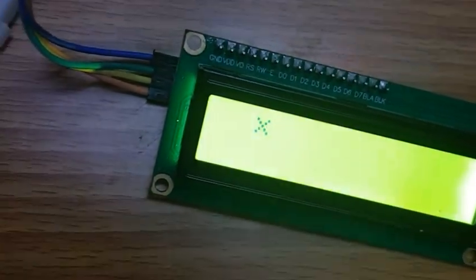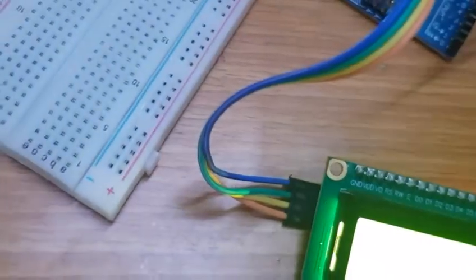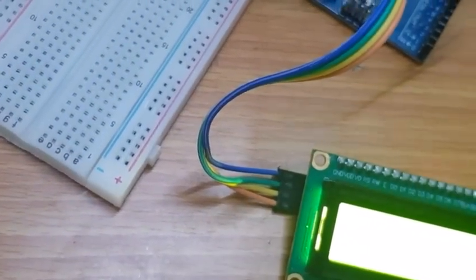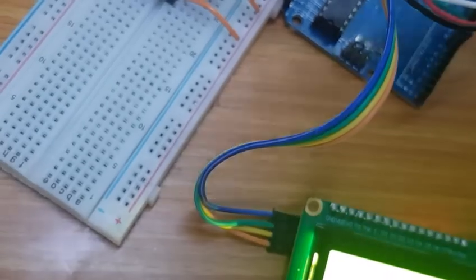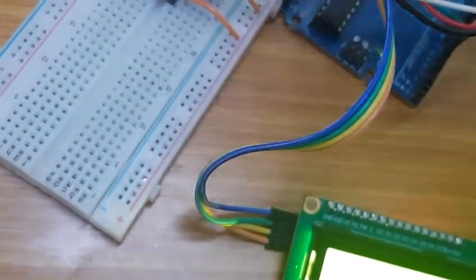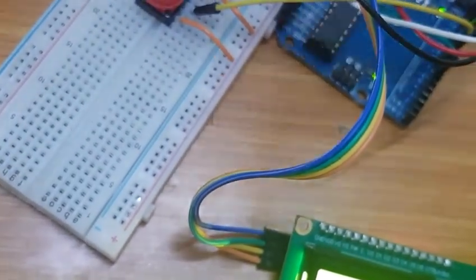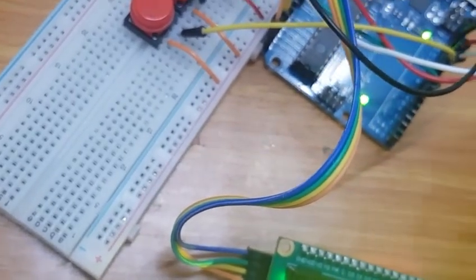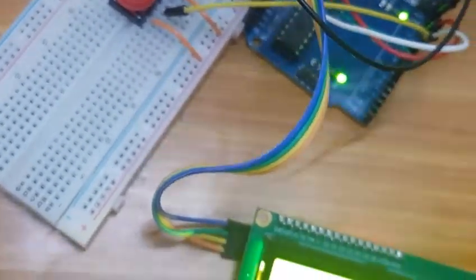And we need to know that it doesn't move beyond the screen boundaries. And there is a slight delay after each movement, that's 200 milliseconds, to prevent fast or multiple unintended moves from a single press. And we need to know that lastly, if no button is pressed, the X stays in its current position and the display remains unchanged.